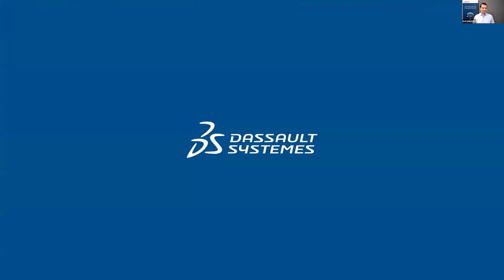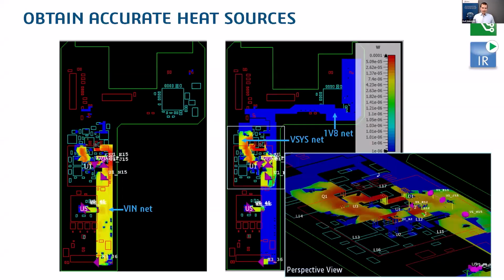So we could easily set up the simulation. We could automatically set up a large number of heat sources, add further details and sources if necessary, set up the mesh, send it off to solving, and so on. And the nice thing about the workflow is that we don't just assume power losses for the most part. We are actually using data from the IR drop simulation as excitation sources.